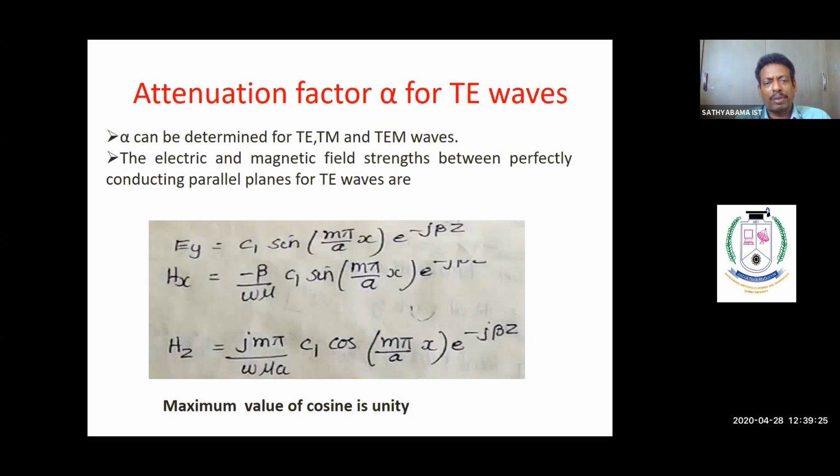So such property if you apply, then you'll get only 3 components. So electric field exists only in the y direction, and the magnetic field is in the x direction. That's a property of that. So electric field is perpendicular to the direction of propagation z. So you have Ey, and the magnetic field is horizontal. So we have magnetic field in the x direction. So we have Hx.